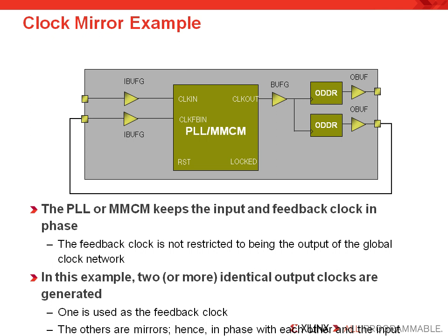You should also keep in mind that the board routing delays for the two output clocks need to be matched in order for all the clocks to be exactly in phase at the various loads for the system to work. For this example, the user would probably build this circuit with the architecture wizard or core generator and then select the compensation equal to external option.